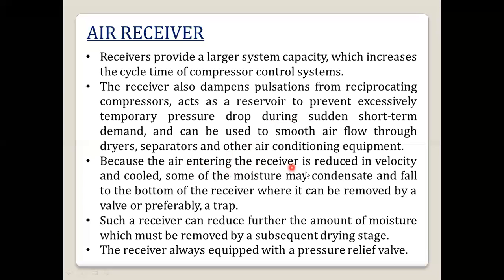The air entering the receiver is reduced in velocity. Okay, so in the receiver the velocity is reduced and it is cooled, and some of the moisture may also condense and fall to the bottom of the receiver, and from there it will be sent to the outside.